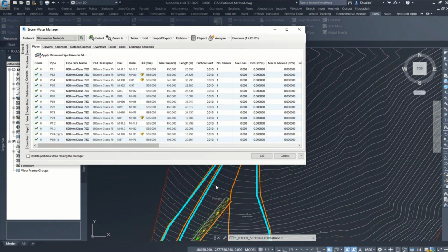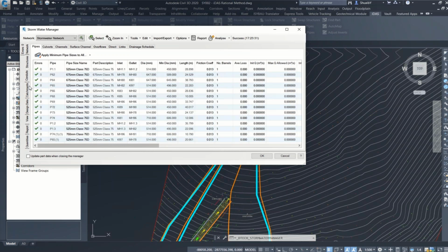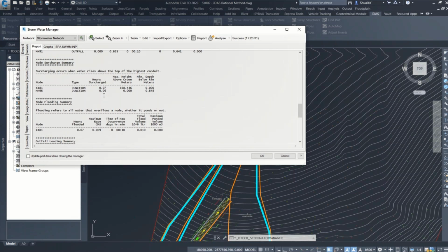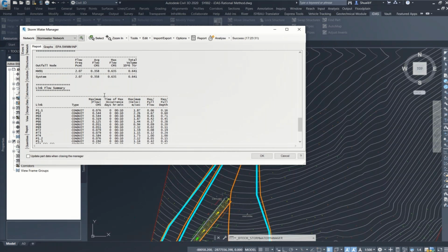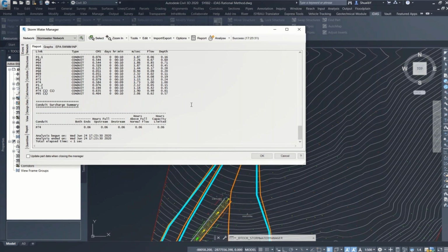So you can see those ones are flagged. I am going to apply a minimum diameter based on the steady flow analysis that we calculated, and it will automatically upsize those if they do not meet the minimum requirements. Pretty great, eh? You don't have to export to SSA or do it from different workflows. If you are a Civil Designer user, you can bring in your data or export your data too as well. So it's a very holistic approach for water design or pipe networks.